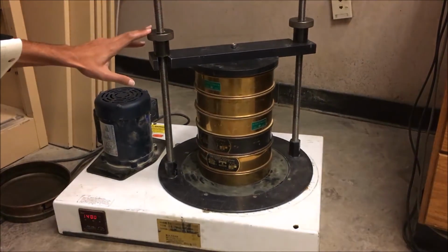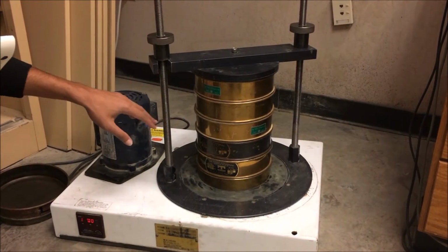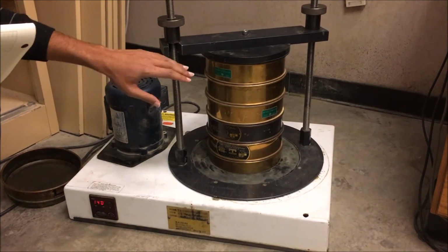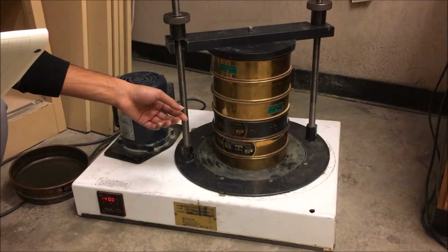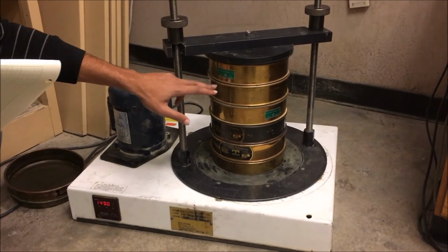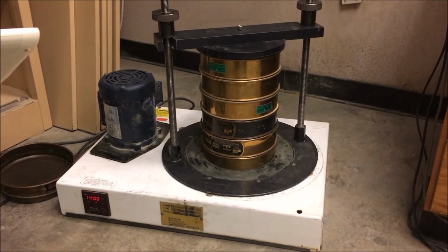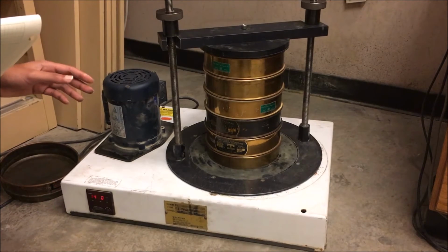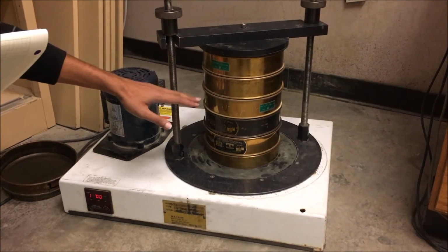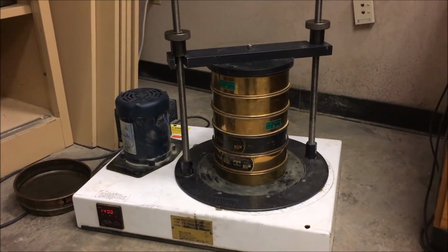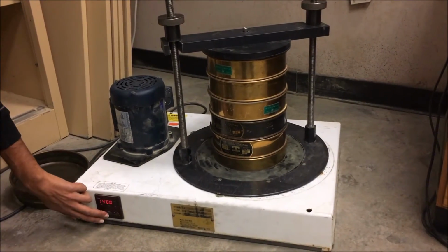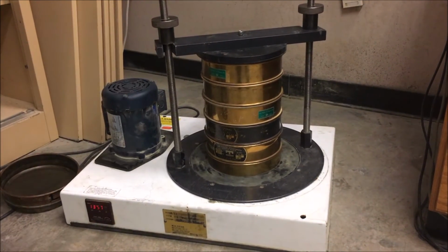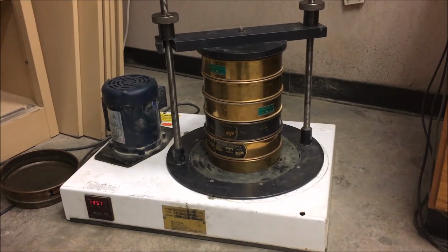Right now we have the sieving machine right here. As you can see, we used 5 sieving layers for particle analysis. Basically what it does is shake the particles, and if we have a particle smaller than the mesh, it will fall down. We did a runtime of 15 minutes, and at the end of the process we weighed the coffee grounds at each sieve to get the mass distribution. Right now I will show you how this machine works. It's just like this, and basically the smaller particles will fall down and we'll get the mass distribution after that.